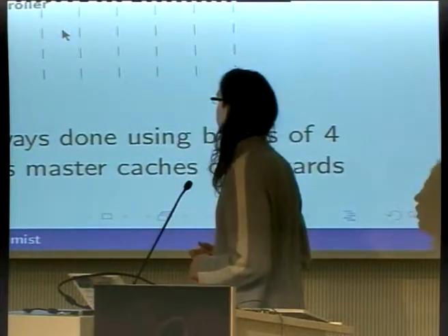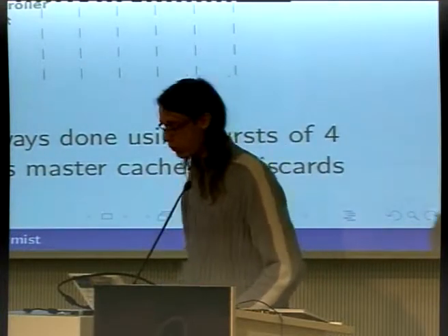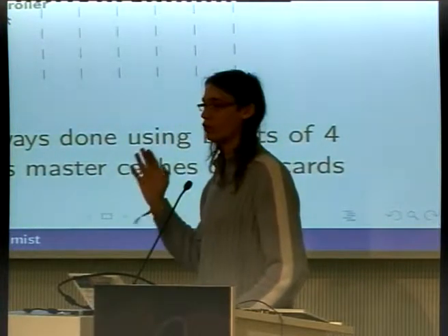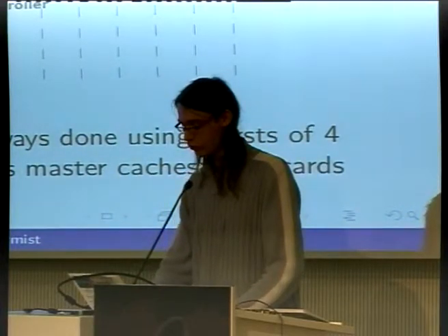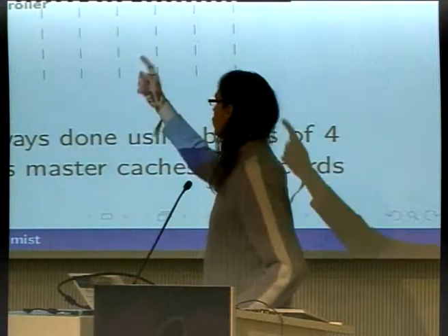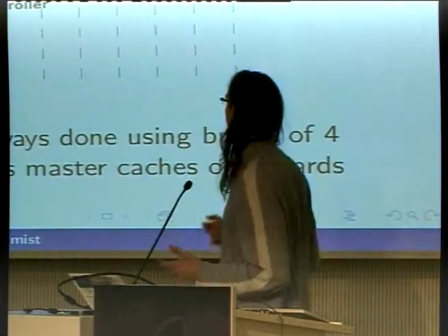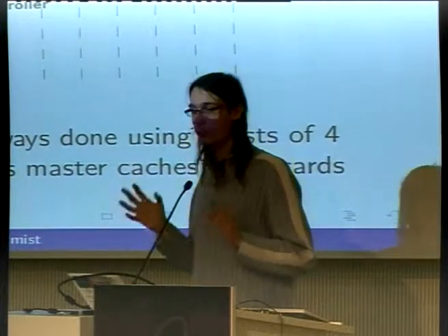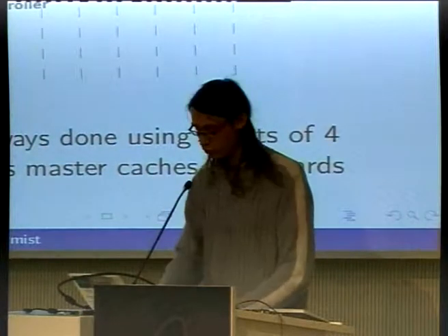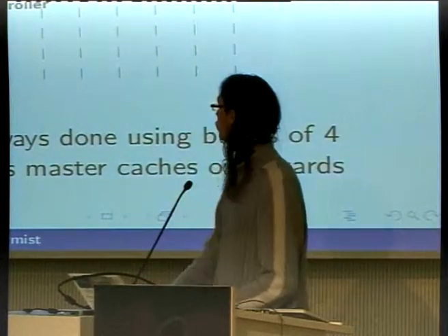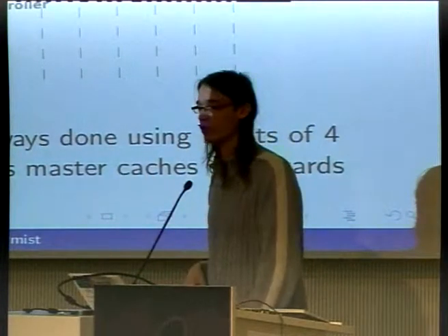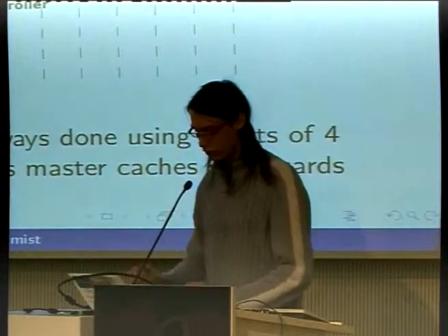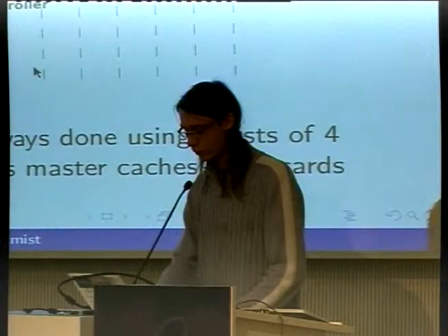And well, you can see it takes a lot of time if you wait for the data before issuing the next command. If you have a more intelligent SDRAM controller, you can issue a read command every cycle, and then the memory will give the data with a bit of latency a few cycles later. And you can see that if you optimize the SDRAM controller, the memory access time will really shrink, and you can really use 100% of the bandwidth, because if you keep the figures that I gave, which is 3 gigabytes for a DDR200 chip, is when every slot is taken here.